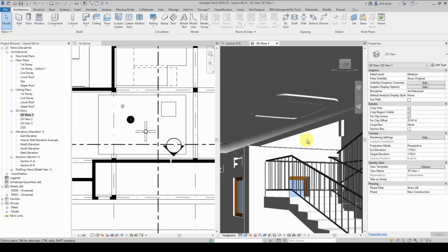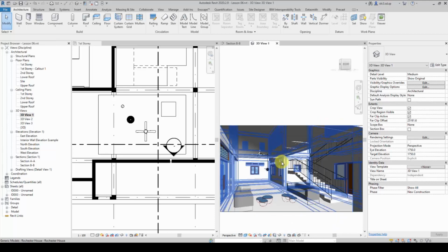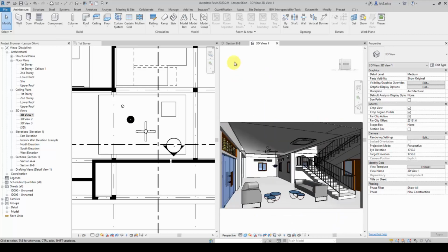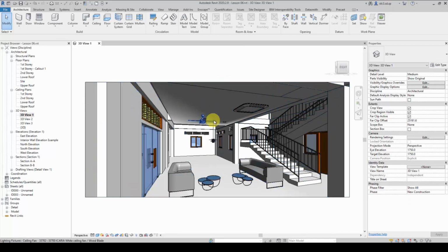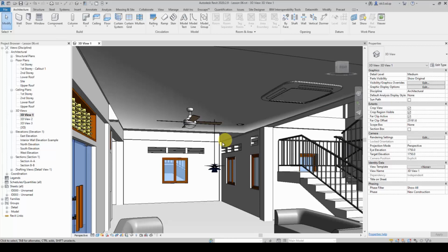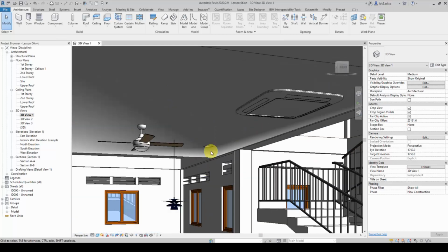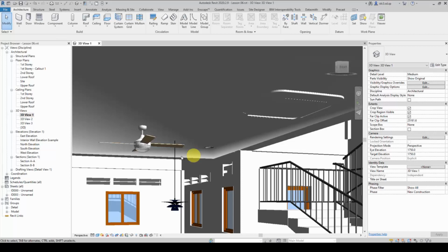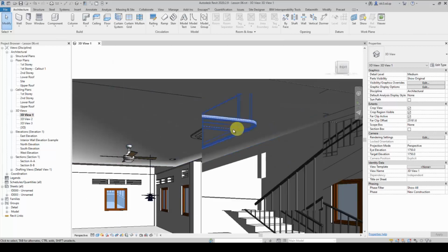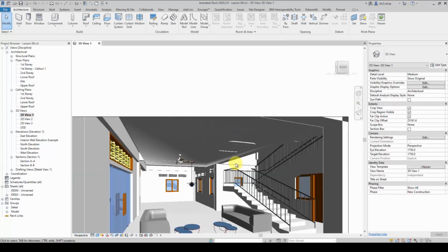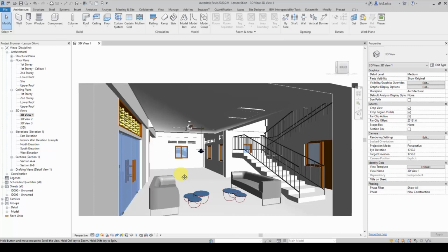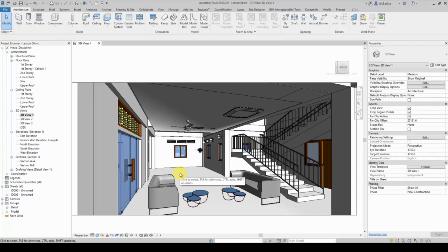But then we can now begin to see this. And again, I repeat, in case it maybe looks better with the ceiling treatment now, I decide to have the ceiling board. So I'm going to click on the review hidden elements and select the hidden ceiling board, which is the hidden element shown in magenta here, and right click to unhide in view elements like that. Okay, and once I'm done, I can turn off the light bulb. The ceiling should reappear again like that.